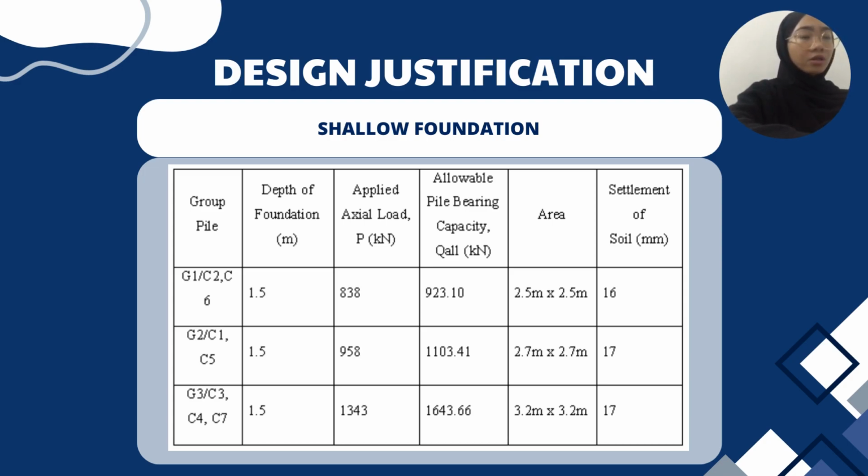So first of all, our group chose Terzaghi's, Meyerhof, Vesic, and Coyle and Castello methods to calculate both foundations, deep and shallow. The factor of safety we assume for the project is 3. Our group chose 3 columns to design for each group, which are C6, C5, and C3.